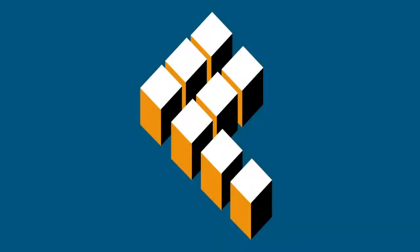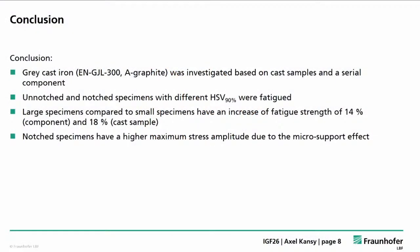We fatigued different specimens with different highly stressed volumes, and we saw an increase of the fatigue strength of the large specimen compared to the small specimens of 14 and 18%. And we've investigated that the notch specimens could bear a high maximum stress amplitude due to the good microsupport effect. Thank you very much, and I am interested in your questions.